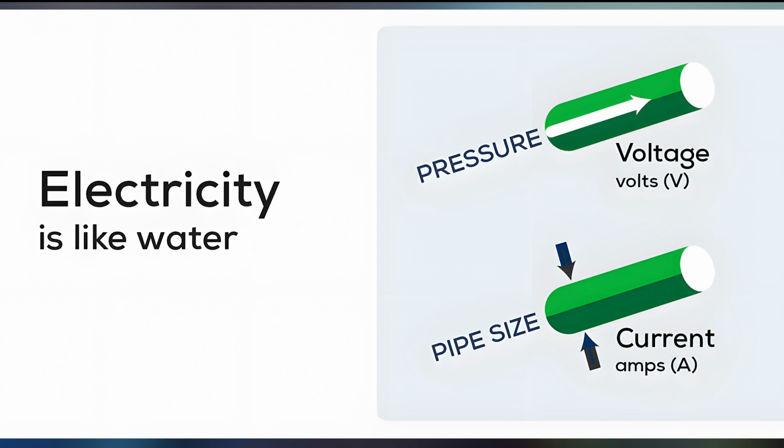That's similar to voltage in that you don't actually have to have a current flowing in order for there to be a voltage. Like if I pick up my battery, suppose it isn't plugged into anything, I'm just picking up the battery. There's no current flowing because there's no circuit there. It's just a battery. But I can still say that there's a potential difference across the two electrodes of the battery, of 6 volts or whatever. So the potential difference exists regardless of whether there's an actual current flowing.